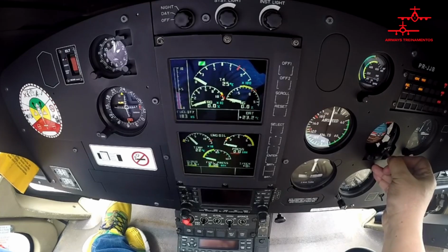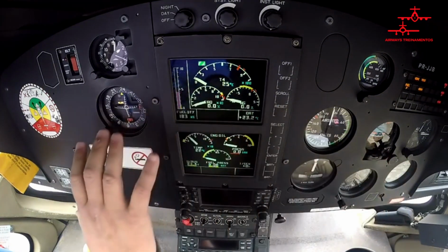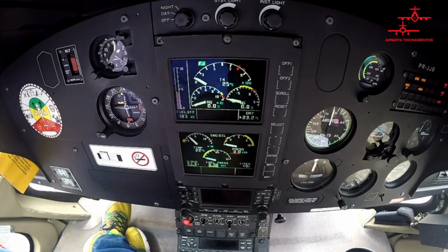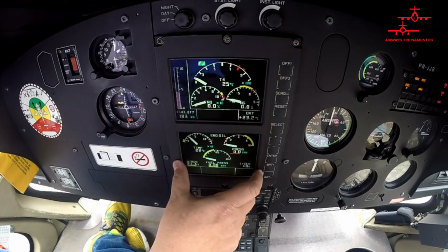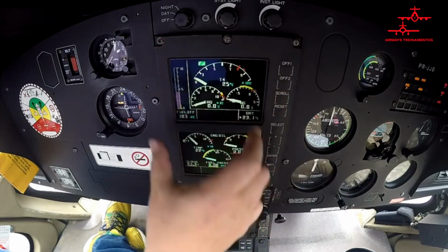It replaces the T4 indicator, NG, torque meter, fuel quantity indicator, oil pressure indicator, and temperature indicator. External air temperature, which used to be a bunch of indicators here on the panel on aircraft up to the AS350B2. So it consists of two screens, an upper screen and a lower screen. Internally, it has three modules, two information processing modules and one display module to generate these images here for the